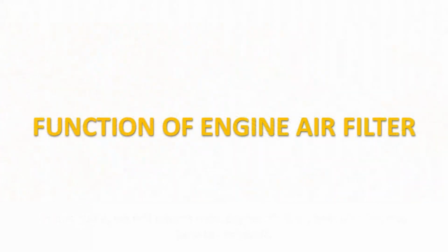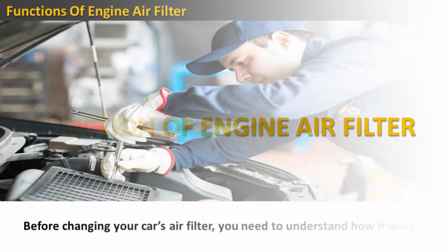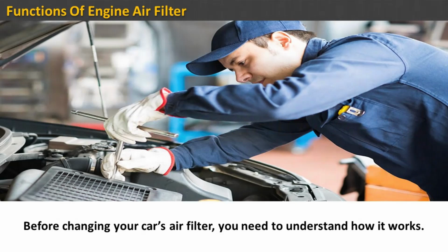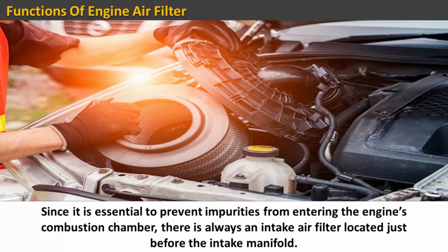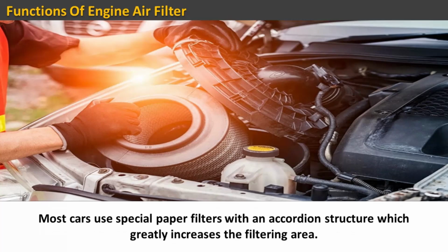Function of engine air filter. Before changing your car's air filter, you need to understand how it works. Air filters clean the air that is drawn in by the car's engine and mixes with the fuel to form the correct compression ratio. Since it is essential to prevent impurities from entering the engine's combustion chamber, there is always an intake air filter located just before the intake manifold. Most cars use special paper filters with an accordion structure which greatly increases the filtering area.